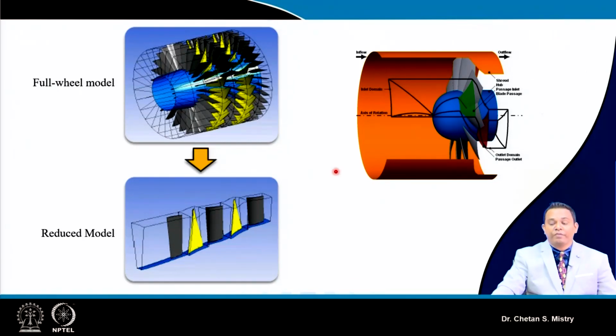So here we need to realize one thing: in order to make our flow domain, the very first important thing required is to make the blade. Up till say week 11, what all we have discussed is in the sense of our preliminary design. Based on the preliminary design, we have come up with the blade and blade geometry at different stations. Now we put that in terms of coordinates, maybe x, y, z, or you can convert that into the r theta z plane. This we will be putting as an input in order to make the solid blade.